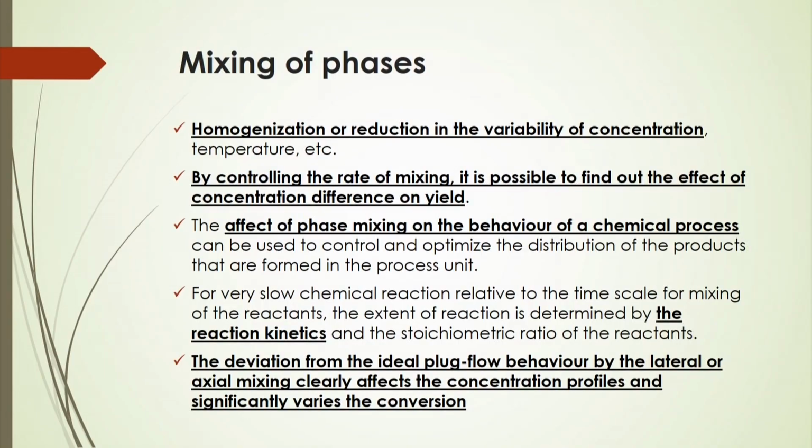In that way you have to know the mixing processes, and to calculate the degree of mixing, generally two parameters are estimated. One is the residence time of the interfaces, like bubbles, droplets or particles, through which the mass transfer happens. The other important parameter is called the dispersion number.